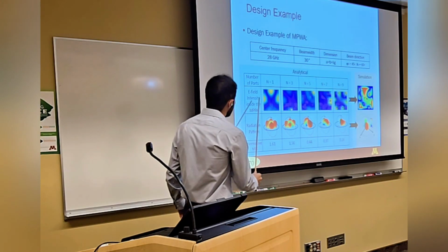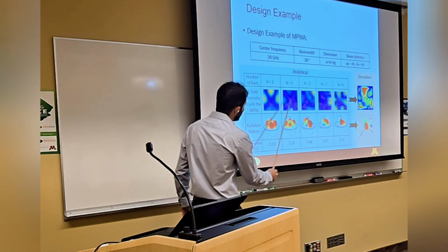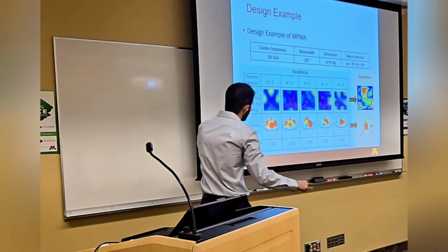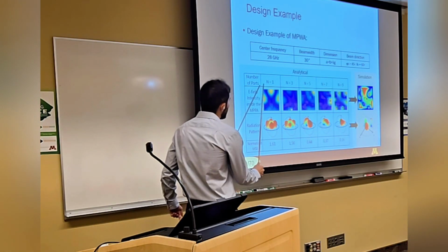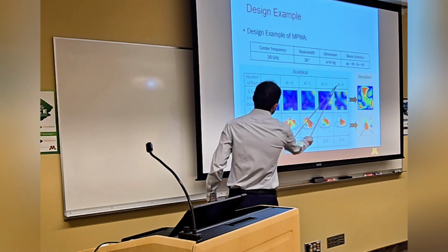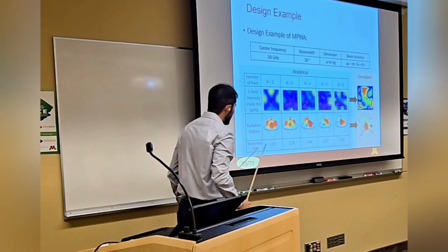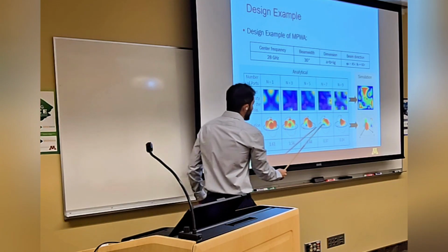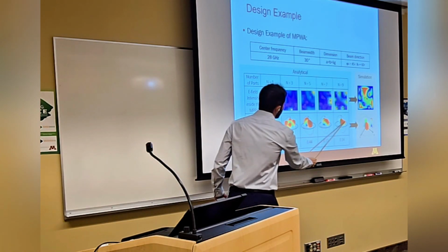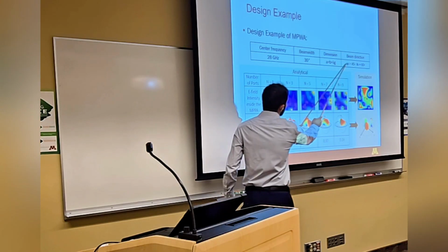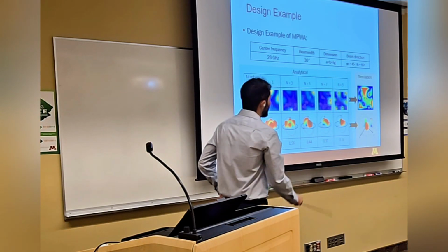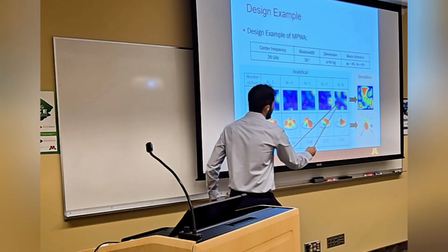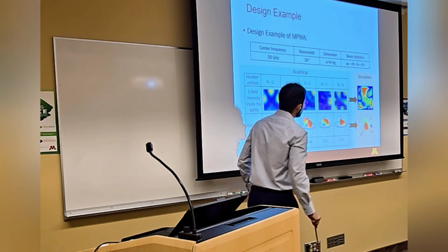And here, you can see the analytical results for each iteration of the optimization process. As you can see, when the number of ports increases, the mean square error metric decreases, and also the analytical result gives us the radiation pattern exactly alongside the target beam direction, and also simulation results completely match the analytical results.